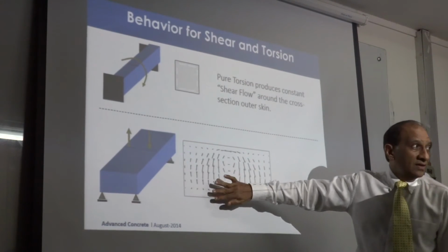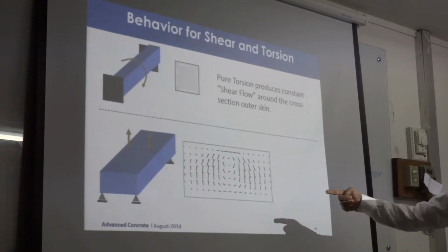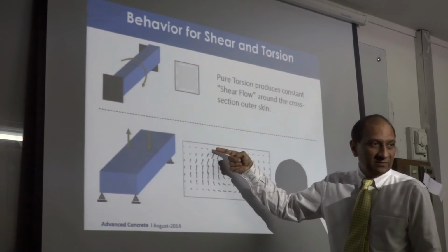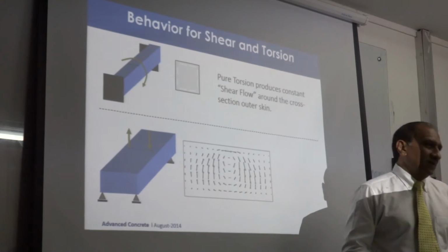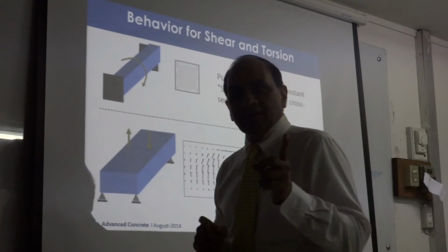Because if the beam is very deep and you have bending moment, most of the beam will be in tension because the neutral axis depth is very small in beams. So it means that if you only provide reinforcement here, the middle portion of the beam will crack. Because you have the whole beam and all of the web is in tension, but you only provide reinforcement at the bottom. Last time I told you about cracking moment and I said spacing is very important. So that means the distribution of the reinforcement is critical.